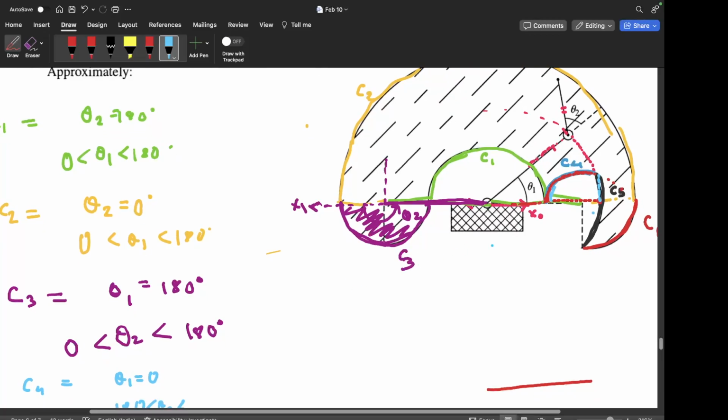Now the other thing which you can see is that when theta 1 is lying here and theta 2 is minus 90, the end effector will be here, right? And then from that place the end effector will start moving, okay? So it will move in this kind of a path, right? From minus 90 to 0, and then from here on it will move inside again, so again it will come to the already covered workspace, right?